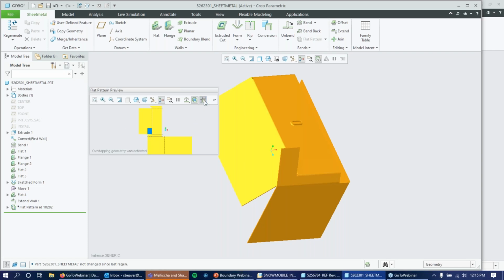Now, if I click these bounding dimensions and zoom out just a little bit, we can see that it gives me the total dimensions of the sheet I would need to create this. And as I mentioned, that will include all the calculations of the radius of each bend, the extra material, that is the extra length that is going to add or take away depending on what you're doing. And also it considers the material that we're actually using. So this is going to vary depending on your material properties, and all of that is going to be calculated automatically.